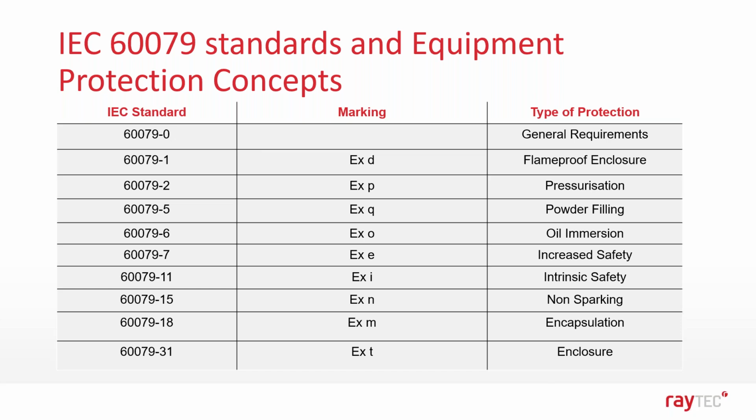So this is where an enclosure is capable of withstanding an internal explosion without transmitting the products of that combustion to an outside atmosphere and hence providing an ignition source for an explosive atmosphere. Whereas 60079-7, or Ex e, that's increased safety, where measures are taken within a product to prevent sparks and excessive temperatures from being able to provide a source of ignition. So as you can see on that table, there's many different types of protection concept for electrical equipment. So it's important to be familiar with these concepts when using hazardous area equipment.